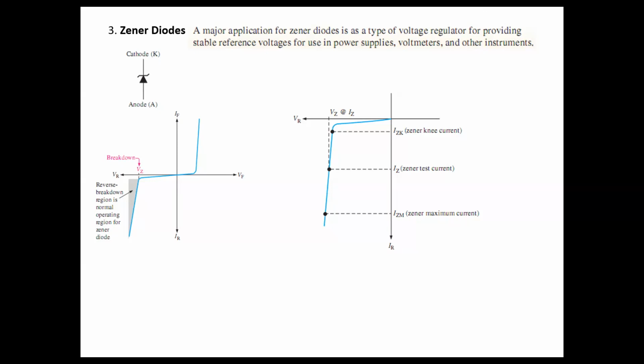For example, other diodes we use like a valve, to restrict current direction, but Zener diodes we use as a voltage reference. So we utilize the reverse bias area of the characteristic curve. We utilize around this voltage, which we call the breakdown voltage. For example, if we say a 5 volt Zener diode, the breakdown voltage of that Zener diode is 5 volts.